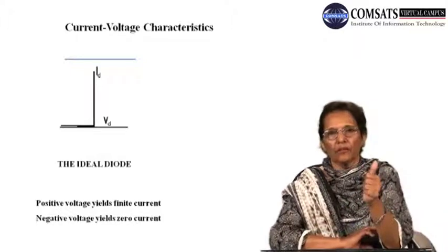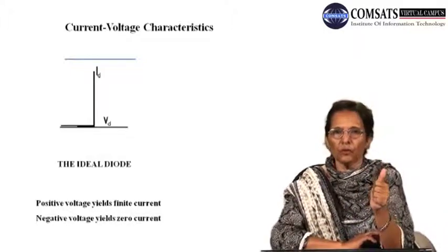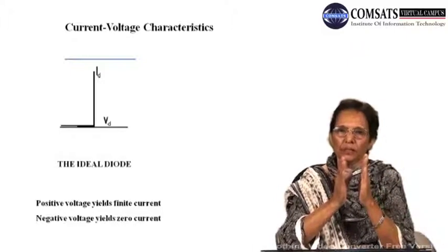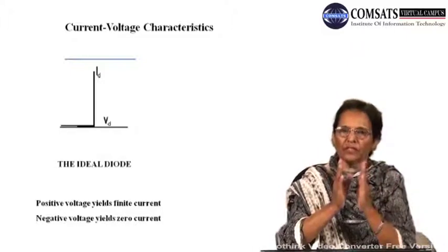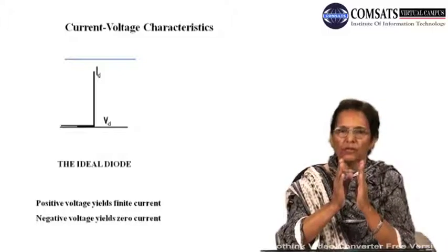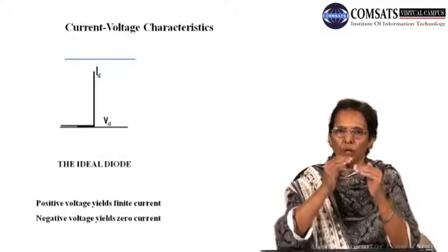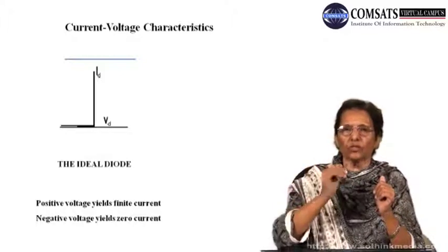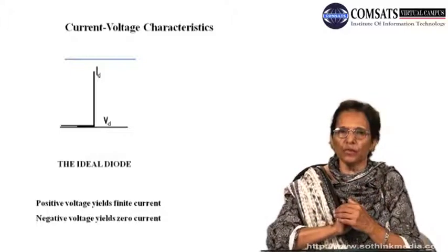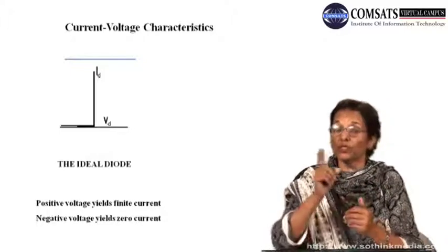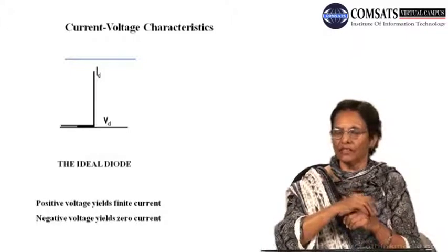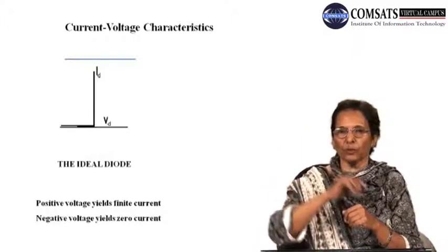Then we move on. We had applied a forward bias. When we apply a forward bias, because of the reduction in the depletion region, the weakening of the electric field within the depletion region, and the lowering of the band bending, more and more electrons and holes will be able to diffuse across the junction, which was stopped in the equilibrium state. Hence the current would increase exponentially.